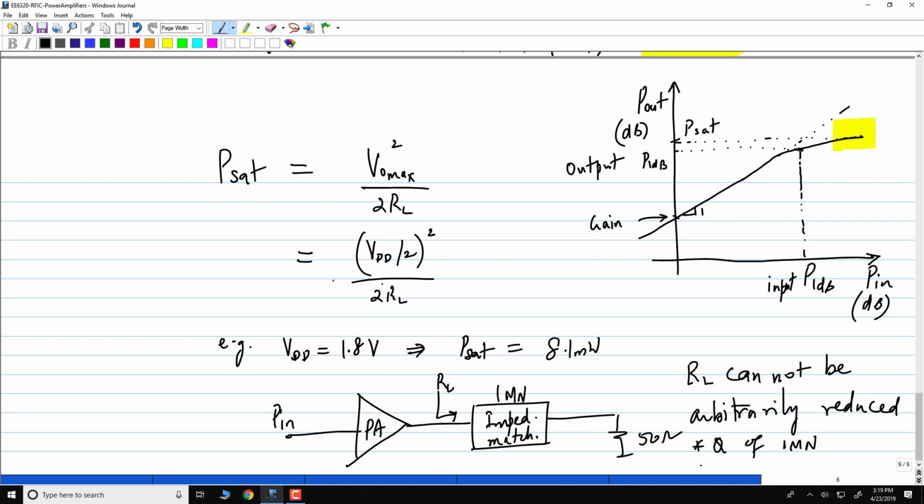Anything else matters? Of course, other, more practical things. If I'm going to lay out the circuit, I need to make connections with wires. The resistance of the wires may be 1 ohm. I need to worry about that. So layout parasitics will dominate a lot more.